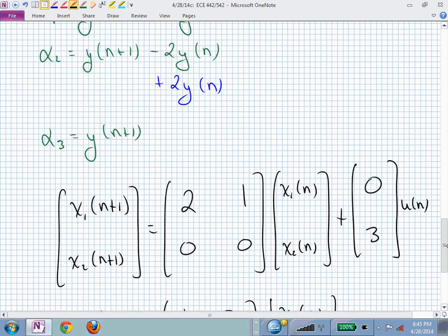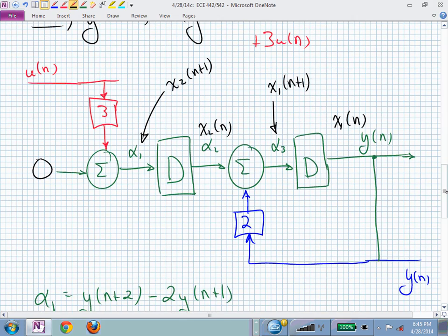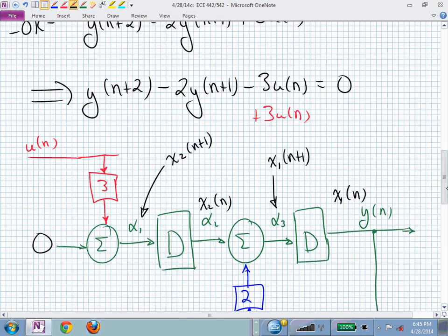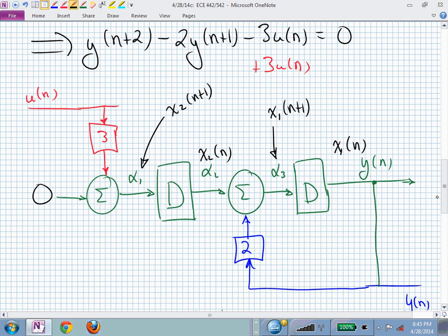And what we're saying with full state feedback is that I have access not just to y, but I can physically now measure x1 and scale that and feed it back, and I can measure x2 and feed that back. Now I have two parameters that are independently scalable, and I can feed back to adjust the dynamic behavior of my system. And we'll pick up at that point on Wednesday.